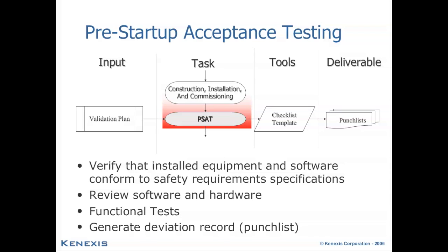We'll do a detailed assessment of the hardware and the software versus the safety requirements spec at this point in time, as well as doing a full range of functional tests on all the installed field devices through the logic solver to ensure the functionality is correct.